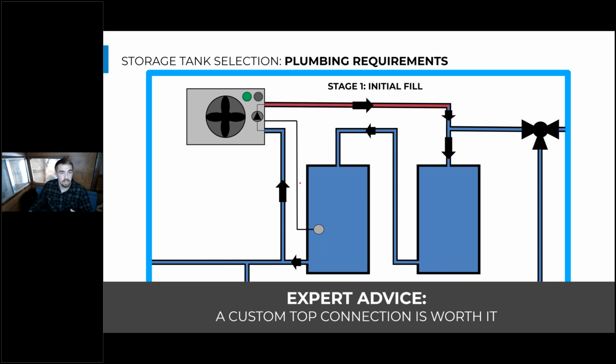So first, if we start with cold tanks and start charging it with the heat pump, we have the hot water work its way down the second tank and then work its way back down the bottom of the large tank, which is actually this first tank. As soon as that hot water makes it through the entire system and all the cold water has been sucked out of those tanks and heated, it reaches the heat pump, and the heat pump knows the tanks are charged because it sees that high entering water temperature.